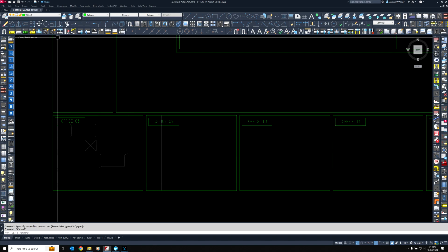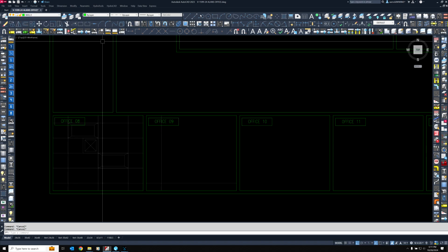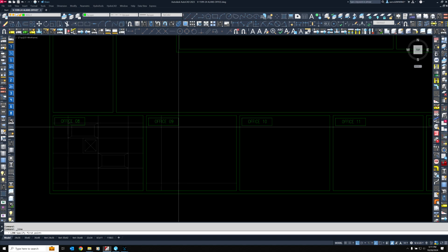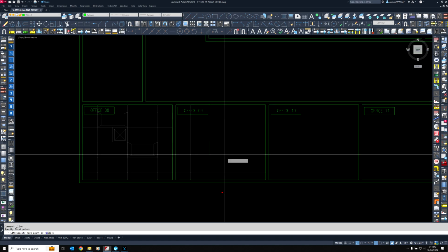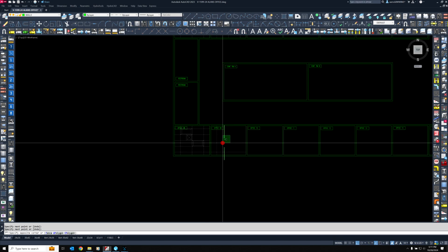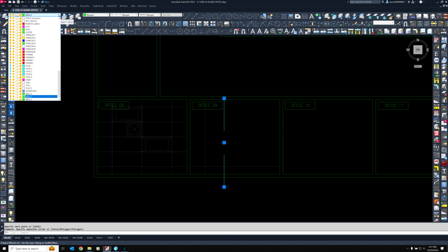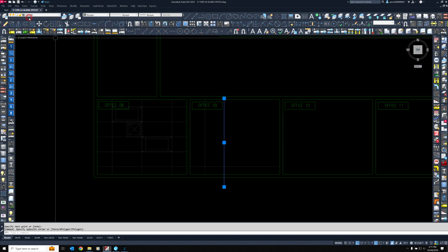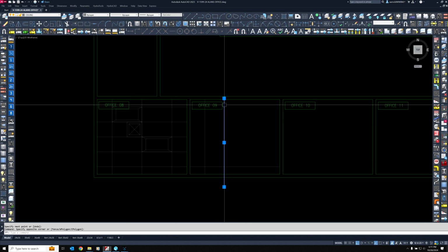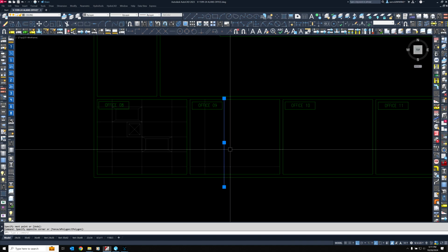I have to make sure that I'm in the ceiling layer. And if you notice, if I had started drawing this and I was in a different line type than I meant, well, first you might notice. But if I want to fix this quickly, I pick that, I use the pull down, I can hit the letter C and it'll jump for me. And then now that is a ceiling layer line. It fixes the weird dash dot, it changes the line thickness when it prints, all that good stuff.